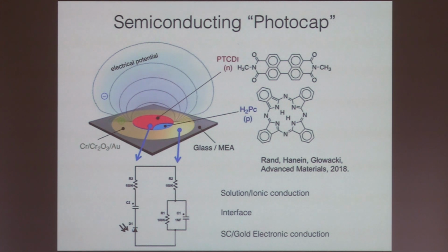This is a very important part of the device because this electrode actually closes the loop with the solution. We used gold, which is a Faradaic material, but in principle you can use titanium nitride or other non-Faradaic materials. Then you have the solution, with ionic conduction. Here you have pretty much standard semiconductor electronic conduction. And here the most horrible challenge, which is the interface.